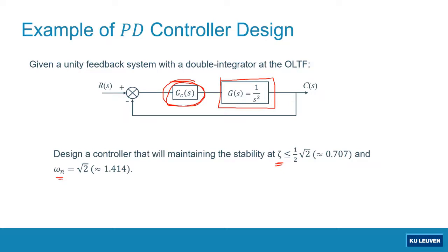So all of these four features that define the transient performance are driven by zeta and omega n according to the formulas. Okay, so whenever you want to improve the transient performance in terms of zeta and omega n, or even in terms of settling time, peak time, maximum overshoot, etc., you have to introduce a PD controller. Accordingly, you have to design an appropriate PD controller.